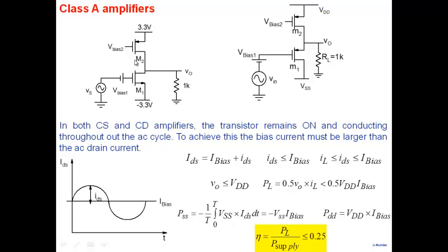A common source amplifier that you see is primarily a gain stage for building up large voltage gain. It's not meant for delivering power to the load here. Now, keeping this in mind, one of the things I've told you is, if I were to design an efficient amplifier, then one of the characteristics it must have is, when there is no input, it should not take any power from the supply. It must have that feature, which means standby power is 0. When there is no input, it should not draw any power from the supply here.